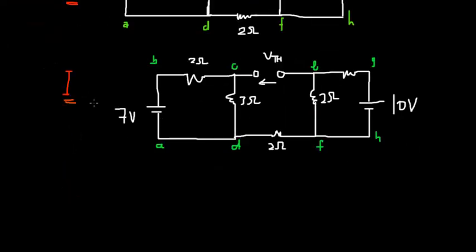Now the next technique is use KVL. In applying KVL we choose loops. So let's choose our first loop from here, but first we need to introduce our current sources. From here we could insert I1 over here. From here you could notice that no current will pass through here, so the same I1 will pass through here, and the same I1 will pass through here also.